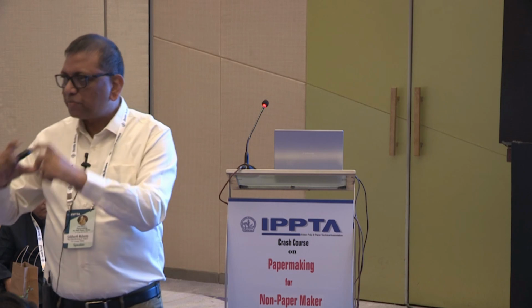You have a release base, then there is a printed one, it will pick it up. The release base will ensure that no glue is sticking here. The glue is intact, so on pressure the glue will get activated. Otherwise you cannot apply pressure on a saline bottle. So that itself will create the pressure sensitive, and your applications will fix onto that.